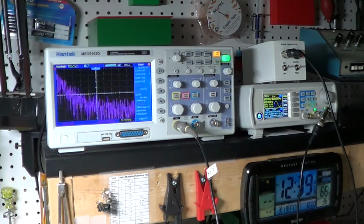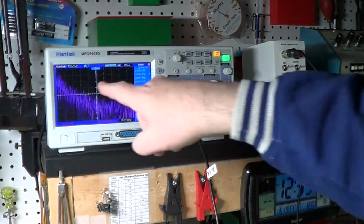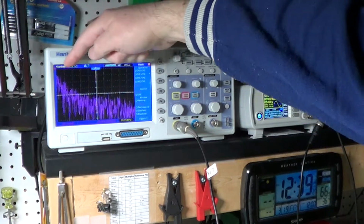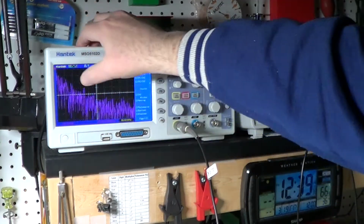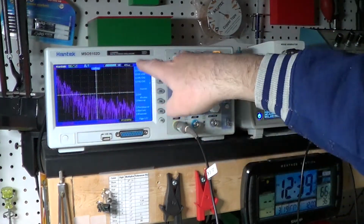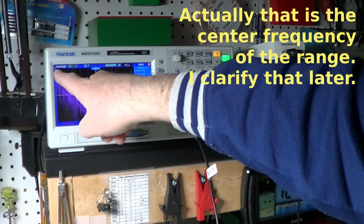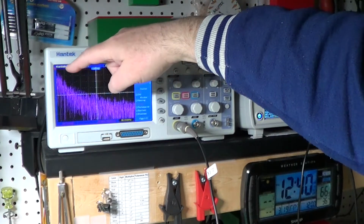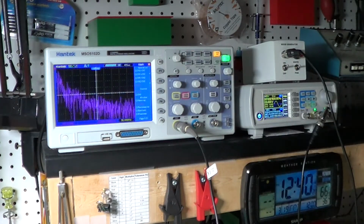Basically, this image shows us how the filter behaves as the frequency changes. You can see for low frequency we have high amplitude. Look at the top of this curve, don't bother with the bottom because the bottom is just the ambient noise, but the top of it is mostly what we want to see. So over here, this is the zero and this is the maximum in this range, which is set right now to 125 kHz. You can see at the low frequencies, the signal has a higher level, and when we keep increasing the frequency, the signal goes to a lower and lower level. A diagram like this is called a Bode diagram.